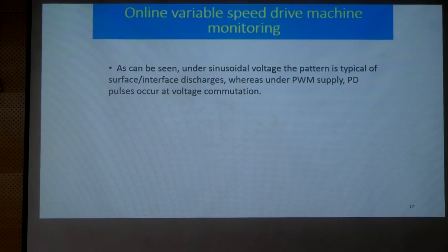So what happens is that the stress in the air medium gets to a very high level. For perpendicular interfaces, E1 by E2 is epsilon R2 by epsilon R1. Epsilon R2 is 4, epsilon R1 is 1. So the stress at this air pocket medium is highly subjected to high stress. Thereby discharges happen, and in that way it gradually deteriorates.